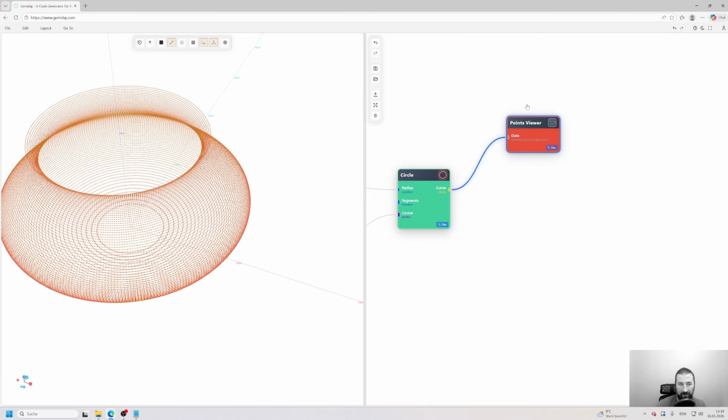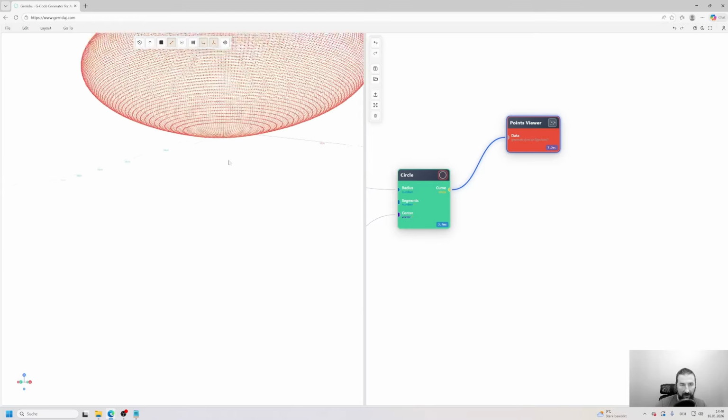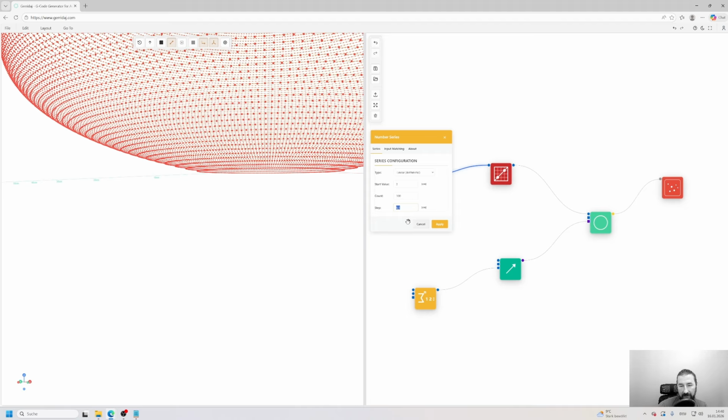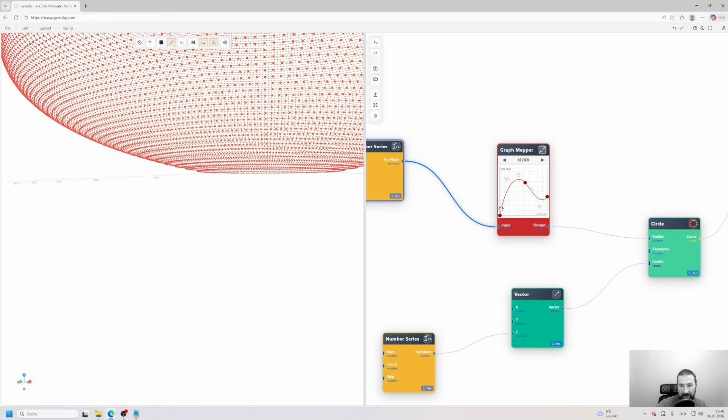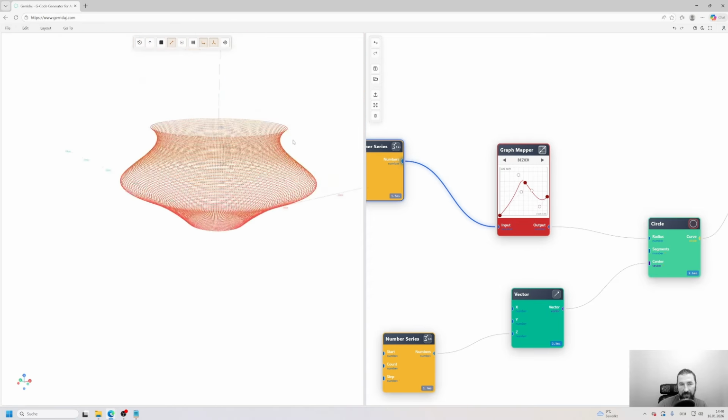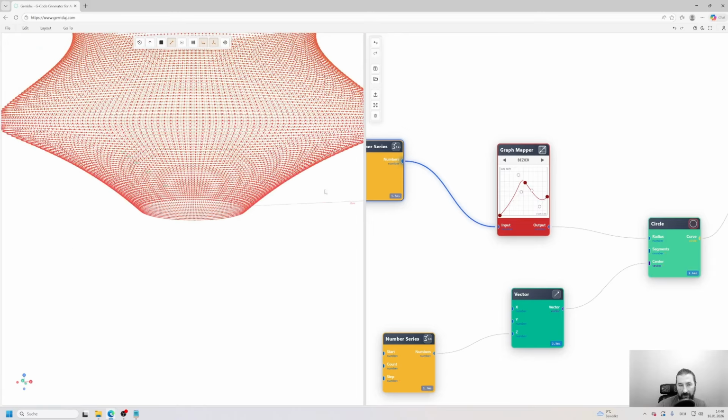Let's reduce the size here of the points. So you see there are some, okay, we have quite a large distance here, it's 1 millimeter. It creates here quite a large gap. It will probably not be printable that way, because the lines are just too far apart and will not stick together. So you need to keep in mind that you can create some designs that will not be printable that way. But if you do it correctly, if you adjust something here, less curvature, so bring the lines closer together, add some modulation so they stick better together and so on. So you have full control here over everything, so you are also responsible for printability of your design in the end.